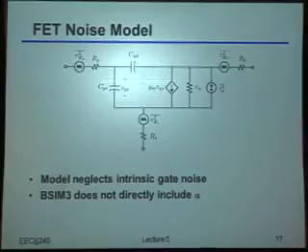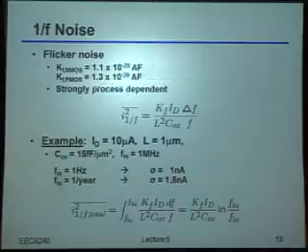Okay, so the last thing I want to mention for this introduction to the different types of noise that we'll be interested in is that it turns out there's yet one more type of noise that can play a pretty substantial role, especially if you're doing very high precision and lower frequency types of circuits. Okay? So this noise is what's called flicker noise, or 1/f noise, or because for whatever reason people like to use color analogies with noise, this is also sometimes referred to as pink noise. Okay? Don't ask me where pink came from. That's just what they came up with for it.